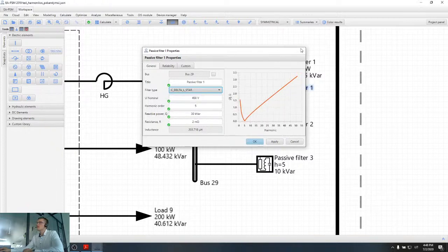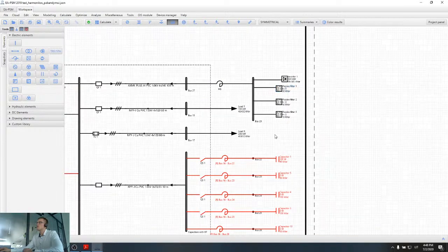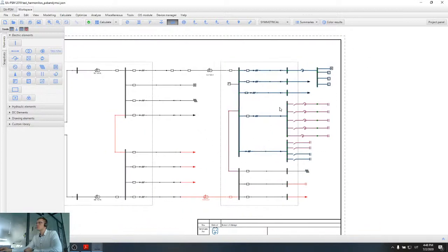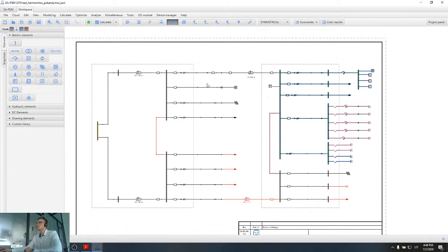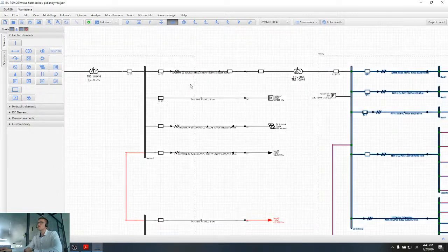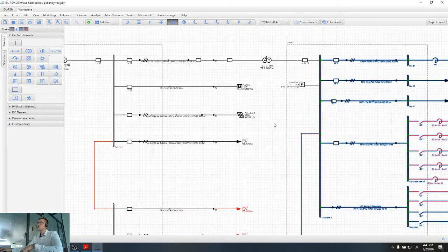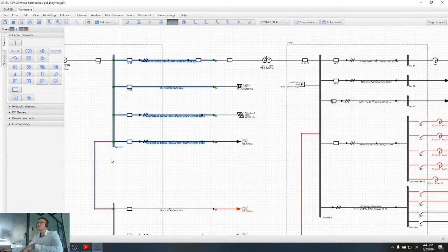However, harmonics are a more local problem and it is best to solve them locally. Most of the harmonics appear in industrial networks, so those problems should be solved in industrial networks as well. All the networks connected to the distribution network generate those harmonics, and each industrial network operator should solve problems inside their network in order to avoid problems in the distribution network.